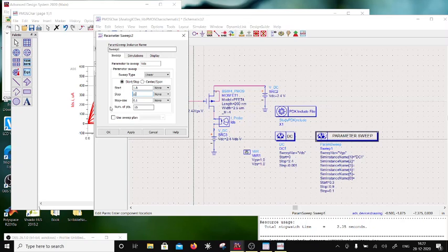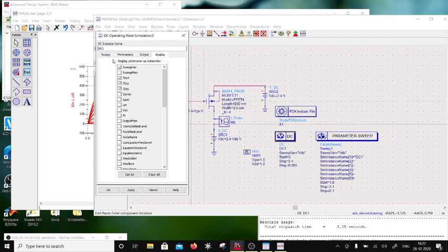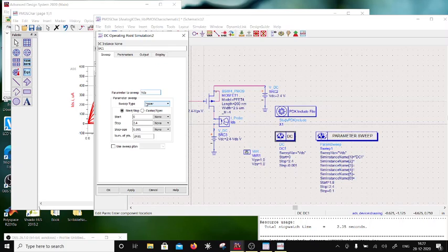So that's what I don't want, right? So I'll go from 1.6 to 2.2 volts. I can take 2.4 volts, 1.8 to 2.4 volts. That's okay, because it comes under a, so net would be 0 here, so that means it will be 2.4 over there. Okay, so there are 7 of them. Say okay, and over here I'm going to sweep VGS from 0 to 2.4 volts.